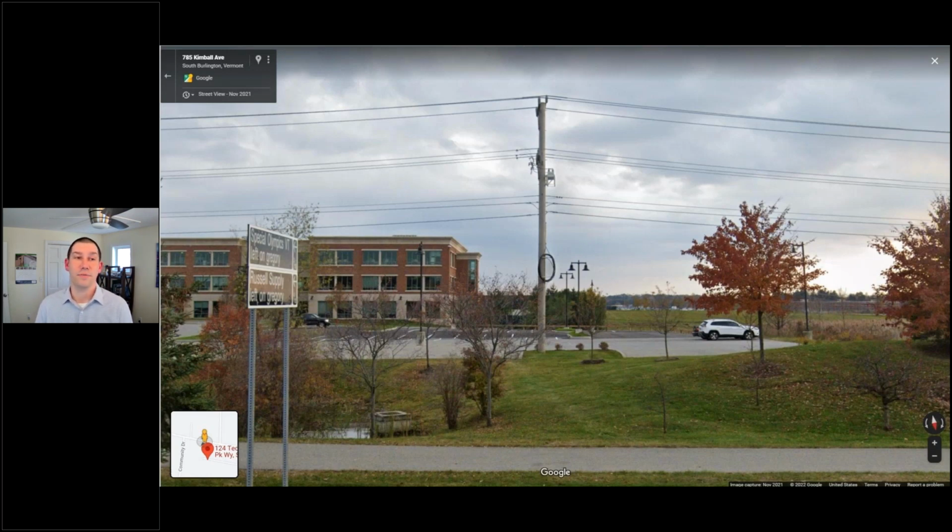And in the last photo for this particular project, which I know is still not up on your screen yet, you'll see some foreground asphalt, which ends up being the finished product for the existing. And then behind that, you'll see the new asphalt. To the left side, if you look left at the utility pole, you can actually see the grade elevation change between the existing parking and the new. Because it was so shallow, they actually raised the grade slightly in that area just to make sure there was a minimum cover, which is only 12 inches for CMP, but allowed them to kind of meet those grading requirements.